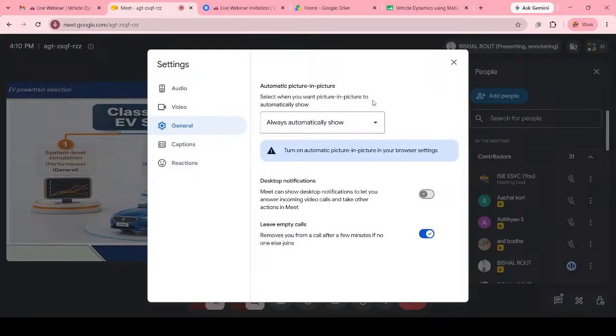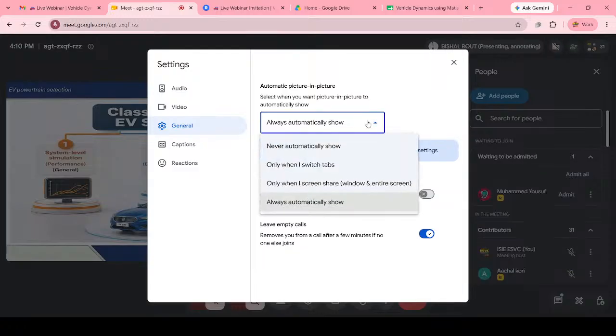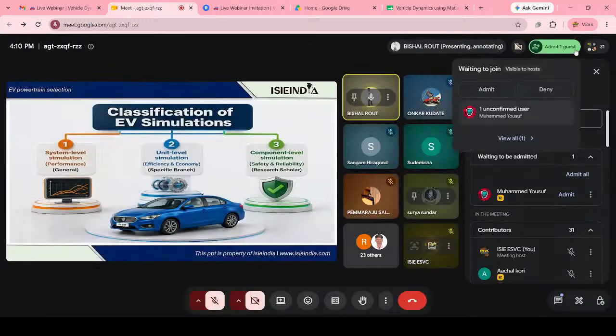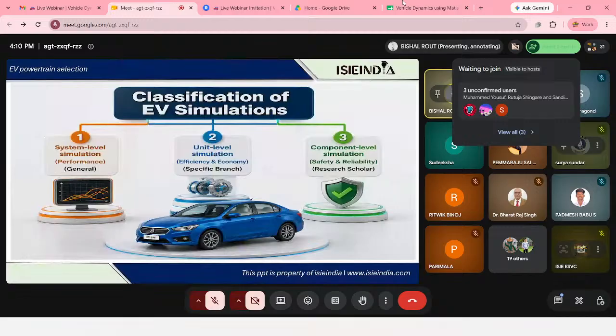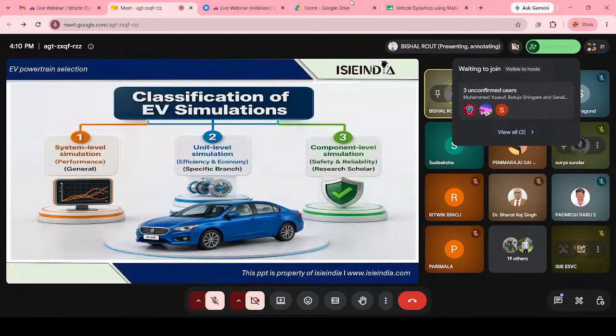A typical system level EV model contains a battery pack, inverters, controllers, electric motors, transmissions, reducer gears, wheels, vehicle body, driver model, road load, regenerative braking, and various vehicle control logic. Instead of modeling everything present inside the inverter, like the transistors, we are not doing that. We are just making a complete integration of all those systems, and then we study what is called system level design.